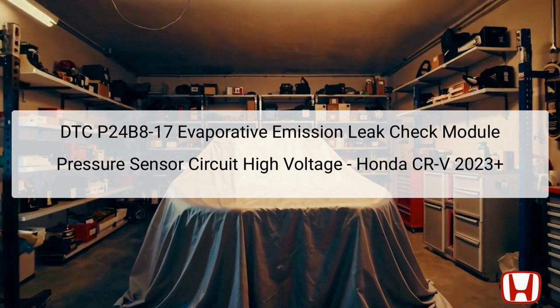In this presentation, we will explore the diagnostic trouble code DTC P24B8-17 that pertains to the evaporative emission evap leak check module. This code specifically points to a high voltage reading in the pressure sensor circuit, indicating potential issues with the evap system of the Honda CR-V model from 2023 and onward. Understanding this code's implications facilitates accurate and efficient repair.